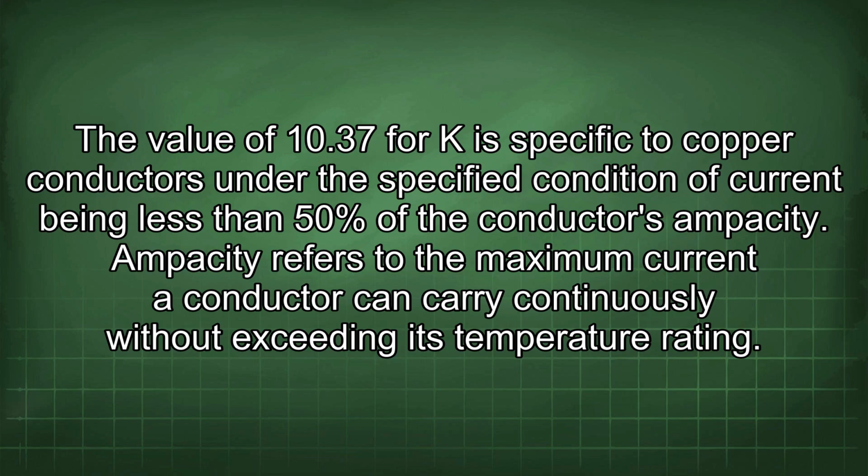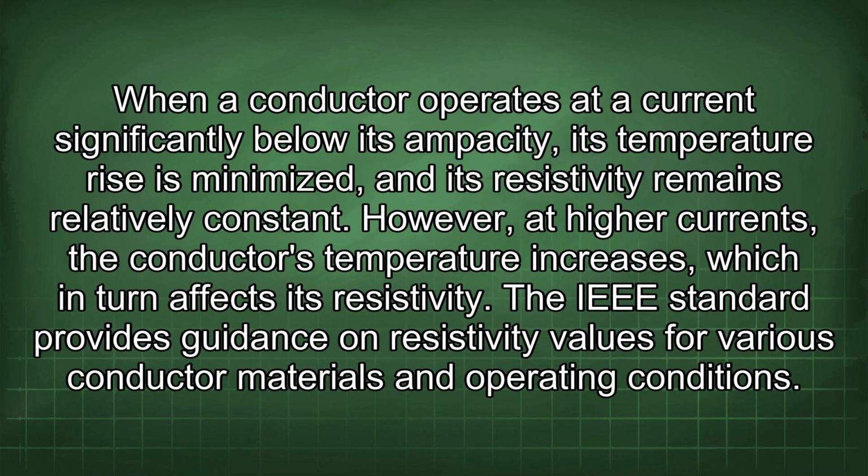Ampacity refers to the maximum current a conductor can carry continuously without exceeding its temperature rating. When a conductor operates at a current significantly below its ampacity, its temperature rise is minimized and its resistivity remains relatively constant. However, at high currents, the conductor's temperature increases, which in turn affects its resistivity. The IEEE standard provides guidance on resistivity values for various conductor materials and operating conditions.